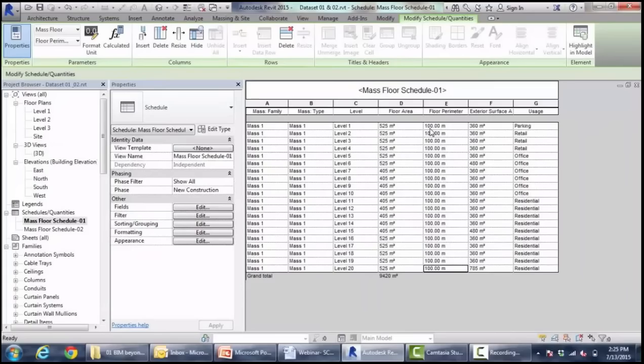I am getting the facade area for each floor. And now I can add some thumb rule parameters, some cost parameters to it. Say for these many floors, I'm going to give external glazing. For these, it would be brick and windows or some other material. So at a conceptual level, you can also compute your cost.